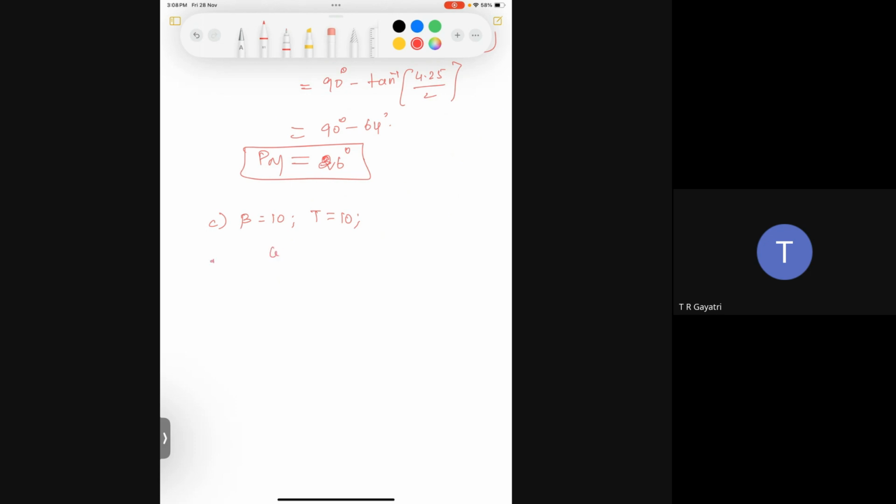Omega GC first we will find. Again, to find the phase margin, we will find the omega gc. It will give me G(s) into Gc(s) equal to 1. Again, we have to do all those things for both. It's a headache only.